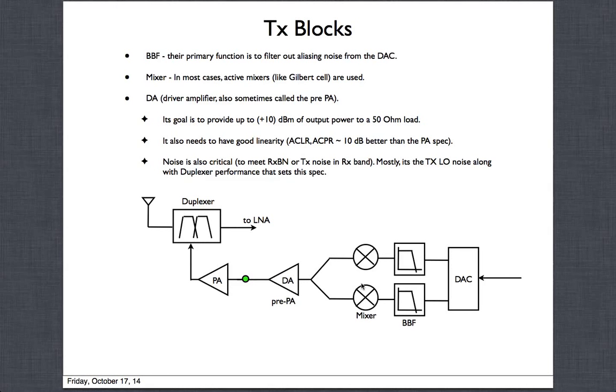And that's the main thing, is you use the same transceiver, change the BOM, meaning bill of material, around it, configure the transceiver using software from the baseband processor, and reuse that same hardware for supporting multiple frequency bands and multiple modes, multiple standards. So it always goes back to the same goal, is how little hardware do they have to swap around, right? That makes it that much easier for them to make these phones.